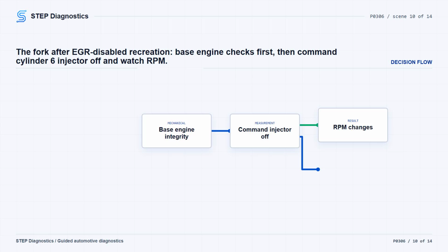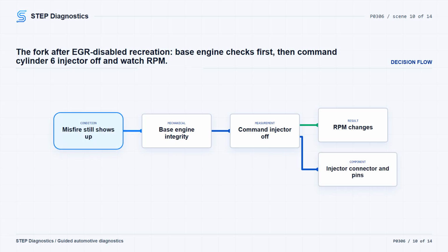Look for things that can disturb cylinder acceleration or engine integrity. Accessory drive drag, a mechanically driven cooling fan where equipped, compression and leakage problems, valve train issues, PCV leaks, other base engine component concerns, and IMRC linkage problems where equipped. Engine temperature may affect these results, so keep that in mind while testing. If a base engine concern is found, repair it, clear the PCM DTCs, and repeat the self-test.